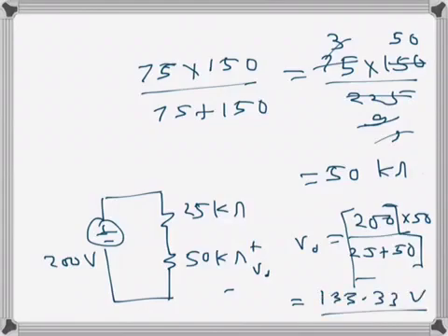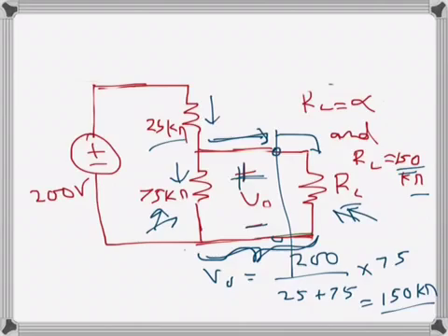We can see the voltage is less now because the resistance is also less. Whenever we connect a parallel resistance, the equivalent value decreases and becomes less than the lowest value of the two, and the voltage drop is also less as a result.